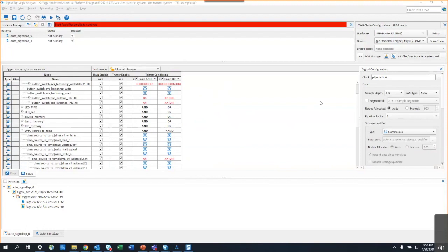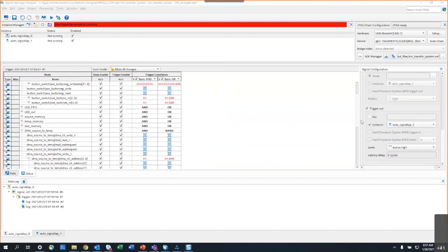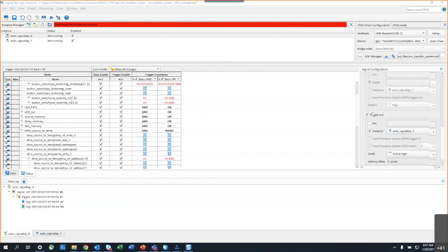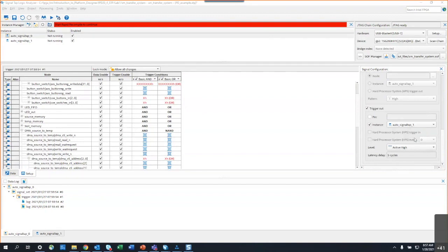while the design is actually running. And then you mentioned SOC use with signal tap. Yes, if you want to highlight that. Yeah, so just real quick, since we are running out of time here, you may have noticed at the bottom in the trigger in and trigger out sections of the logic analyzer. For trigger in, the HPS can generate a debug signal input to signal tap. So an event can happen on the hard processor that can be used as a trigger into signal tap. And also signal tap can generate a trigger in signal to the HPS.